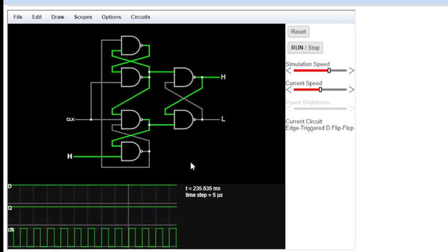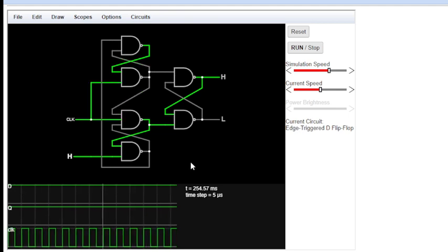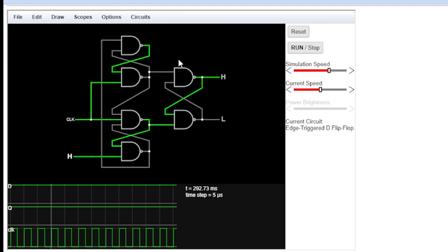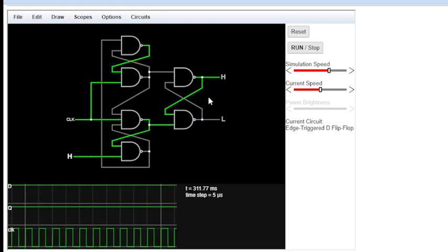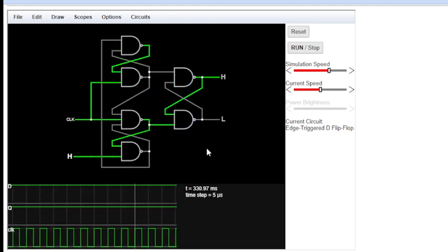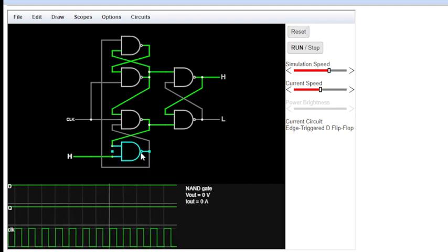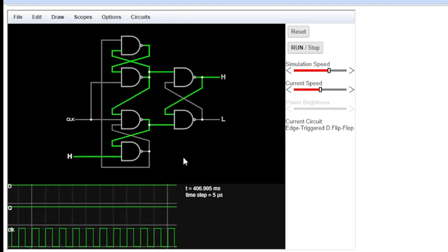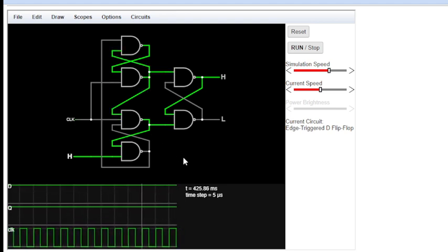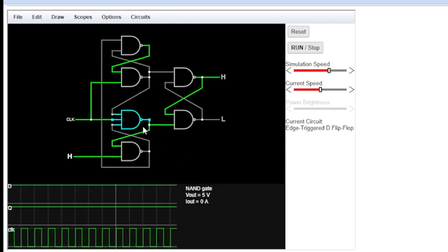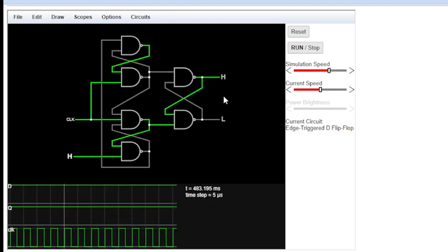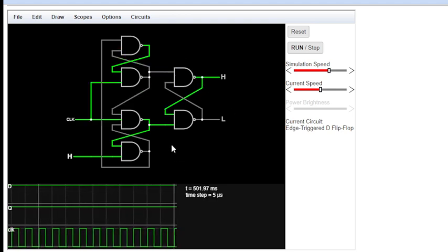As you can see here, basically these are the combinations of three SR flip-flops. So simply we have to memorize this circuitry only, and we have to draw this circuitry three times. Now, you have to memorize that the upper NAND gates always give us the output as Q. You can see this one is Q1, this one is Q2, and this one is Q. Okay, now what's happening here?